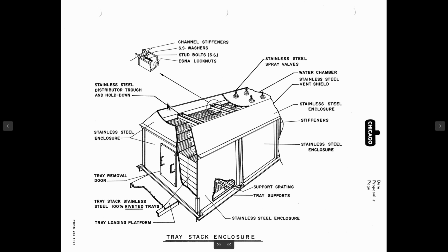This is inside the deaerator. The part that we would see would be the deaerator enclosure, the pressure shell on the outside. Inside of it, you'd go through the manway door. Then inside here, you'd have your access door for all the trays. Spray nozzle sat up here. This would be the water chamber part.